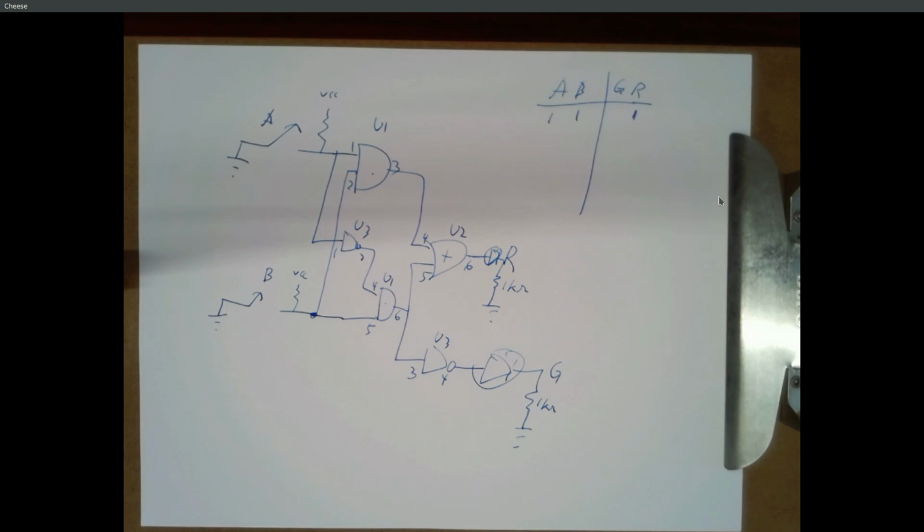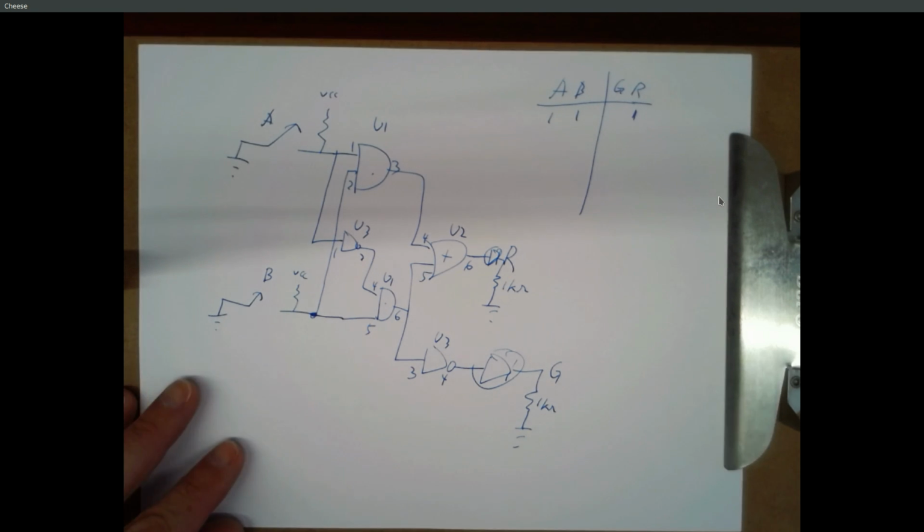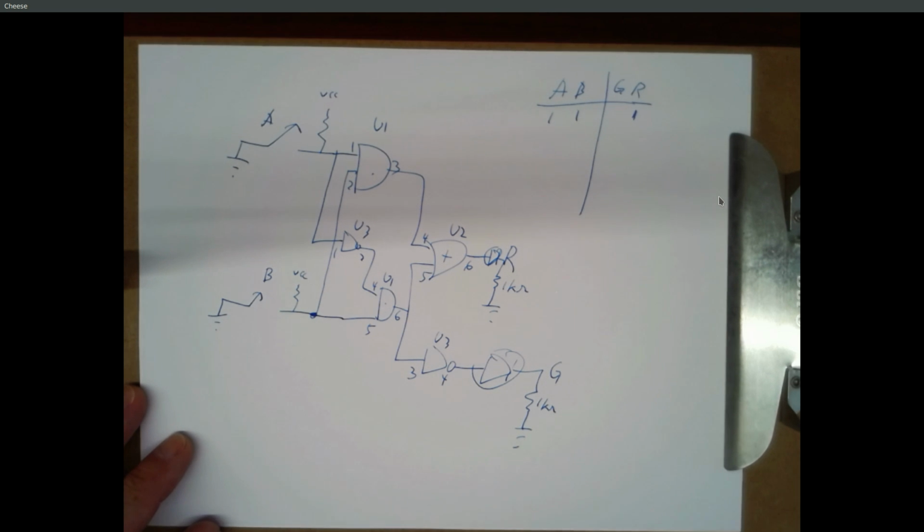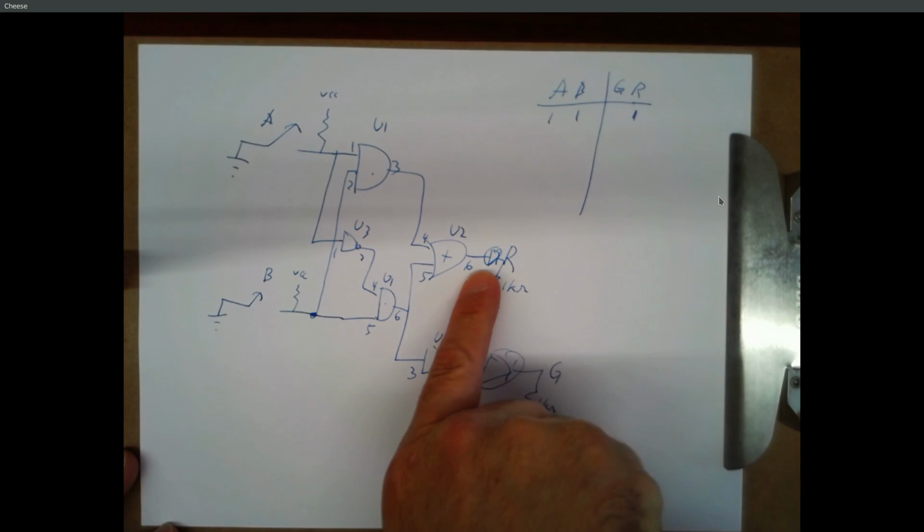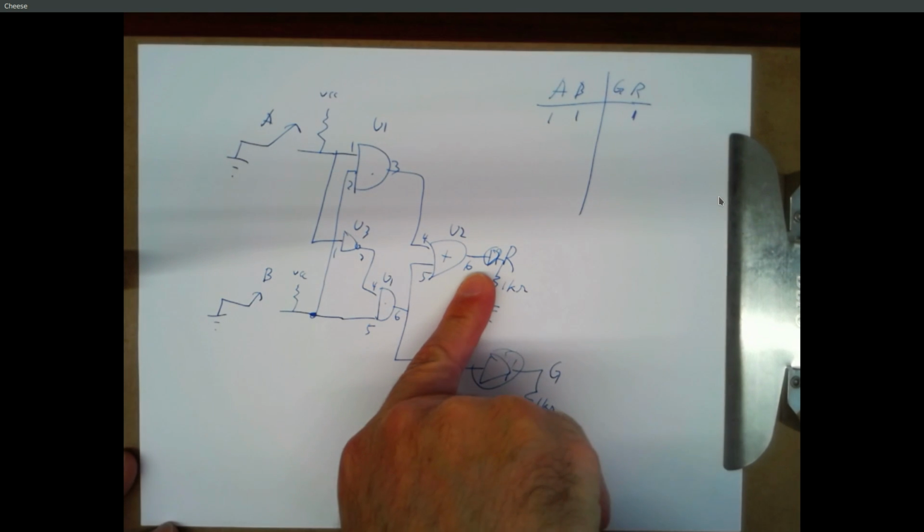And then take the other probe, connect that to an alligator clip, connect it to a wire. Okay, so the first thing you do, take that wire, that's your probe, you can put that anywhere in your circuit board and read the voltage, right? Put your multimeter on voltage, flip down the stand so it's just standing up so you can look at the display easily, and put it right here on pin 6 of U2.